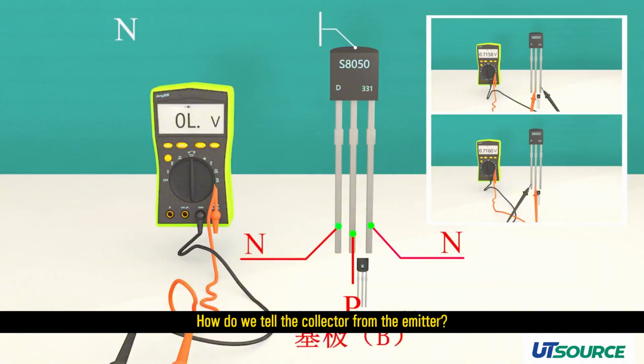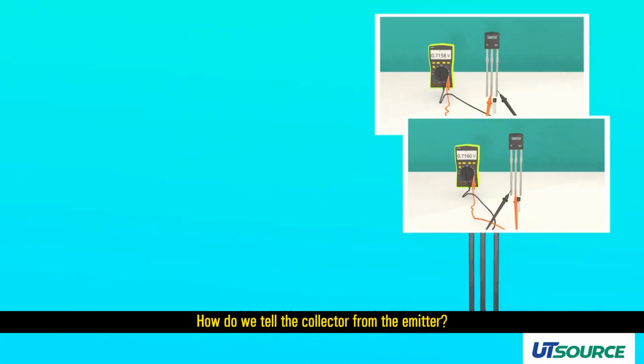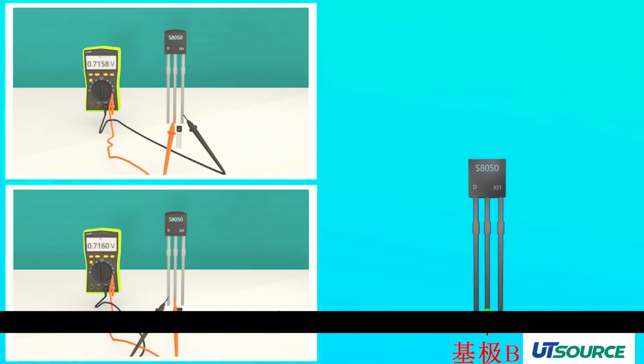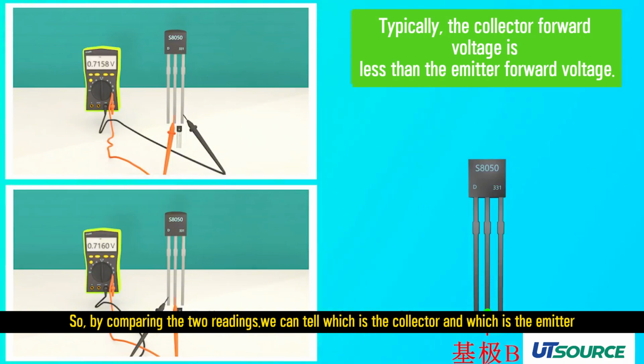How do we tell the collector from the emitter? Because the carrier concentrations in the two PN junctions differ, their turn-on voltages are slightly different. Just remember, the collector voltage is slightly lower than the emitter voltage. So, by comparing the two readings, we can tell which is the collector and which is the emitter.